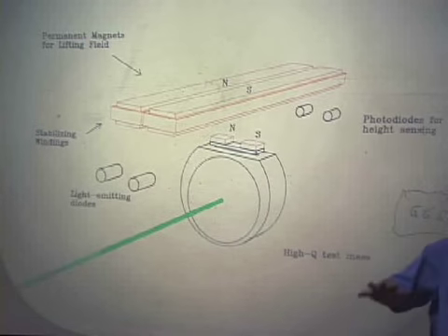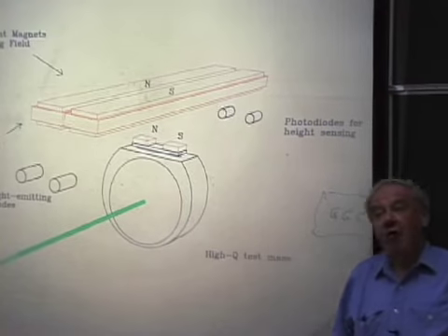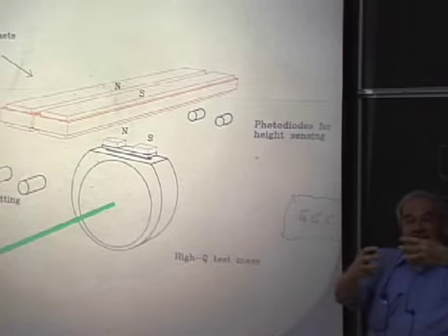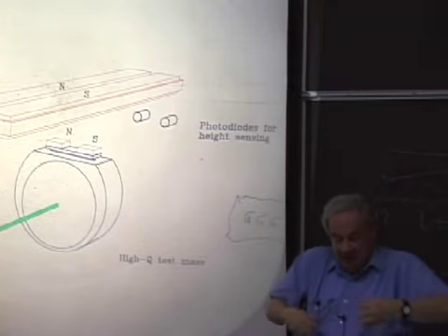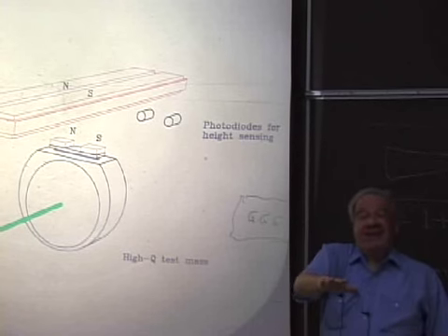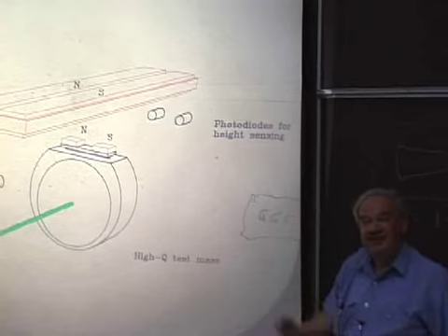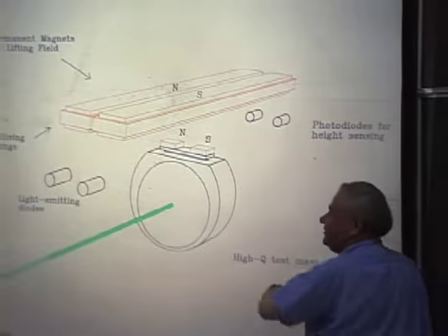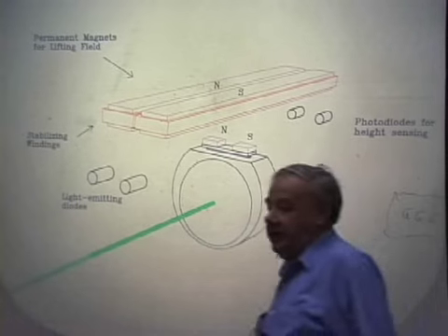As soon as you get that working, what you find is, of course, with this long period, it's very sensitive to tilt. If you walk into the room and this thing is there, the thing has to come towards you. But it's not because your weight's attracting it. No, it's because you're depressing the floor, even though it's a basement solid floor. It's tilting the whole thing, and the thing is running downhill towards you, and that's why it comes towards you. So such a thing with a long period is very sensitive to tilt to the ground. So the next step is to control that, and that's what we did.